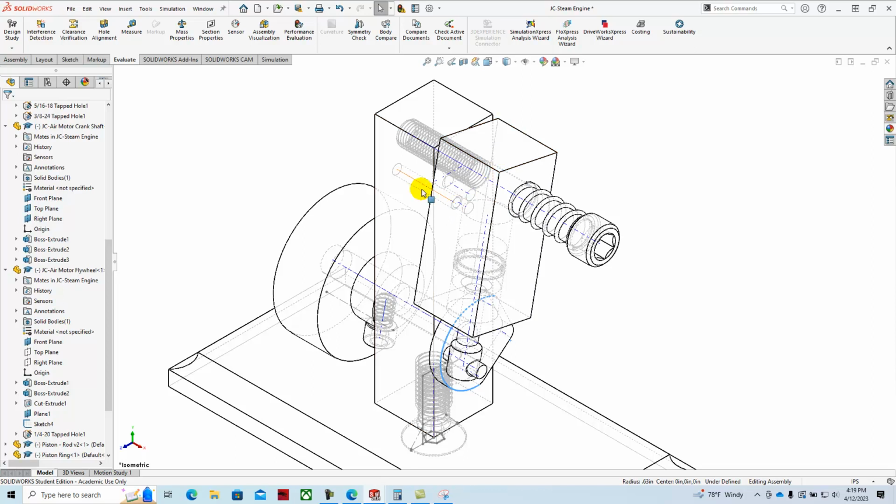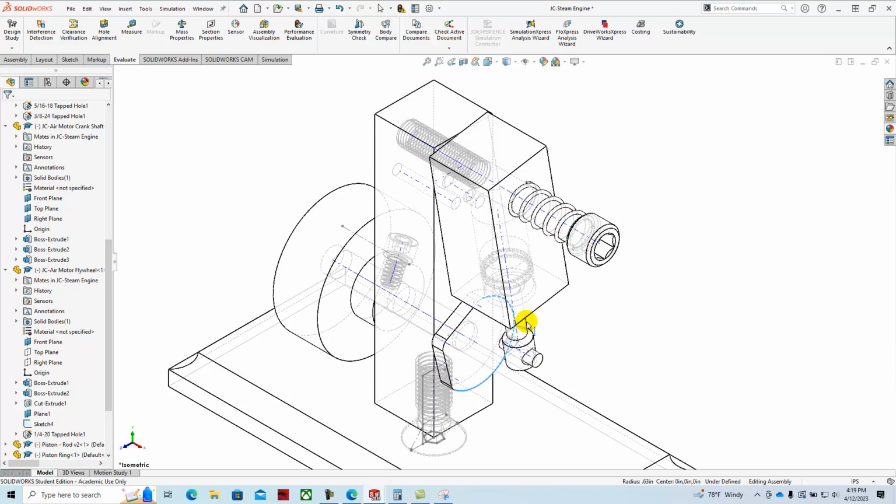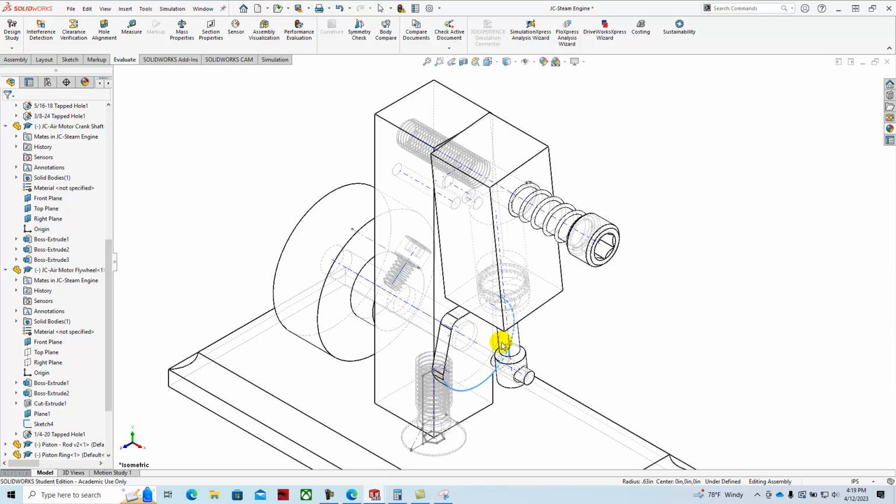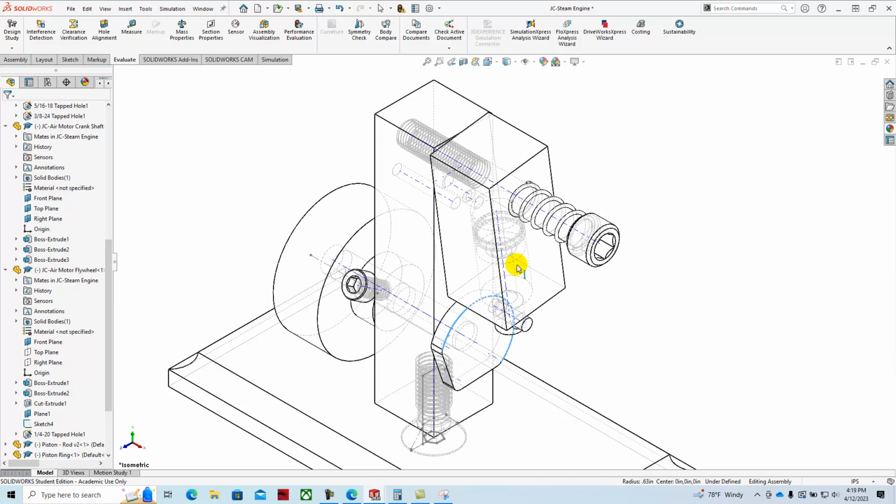And so it wobbles back and forth, and we control the tension with this threaded bolt, and the pressure is kept on it with this spring. So as we go through and this turns up and down, it continues to cycle and exhaust.